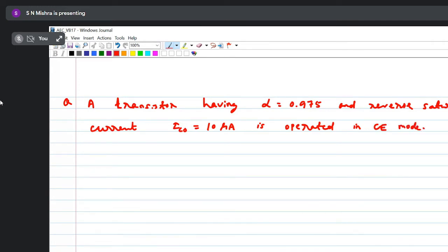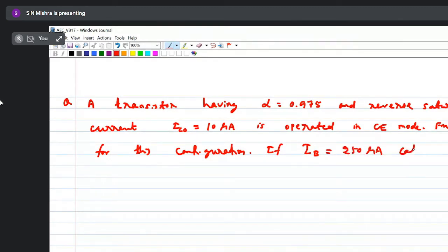And next is optical add and drop multiplexer. So the function of this optical add and drop multiplexer is to add, that is insert, or to drop, that is to extract, one or more required or desired wavelengths at a particular designated point in the optical domain. So here for this add and drop, we use MEMS, reflecting mirrors. We use reflecting or miniature mirrors.